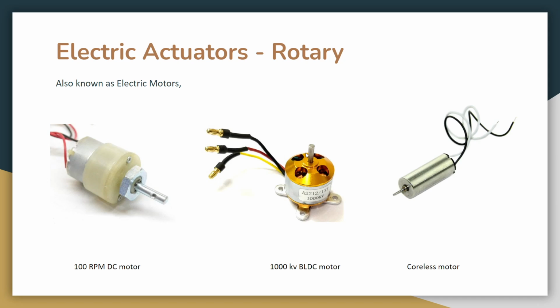If the propeller is too long, too big and heavy, I really shouldn't put it on a motor of 1000 to 2000 kV, and definitely not on motors of 2000 plus kV rating. If the motor is rated 2200 kV, it has to rotate at 2200 rotations per minute for 1 volt.